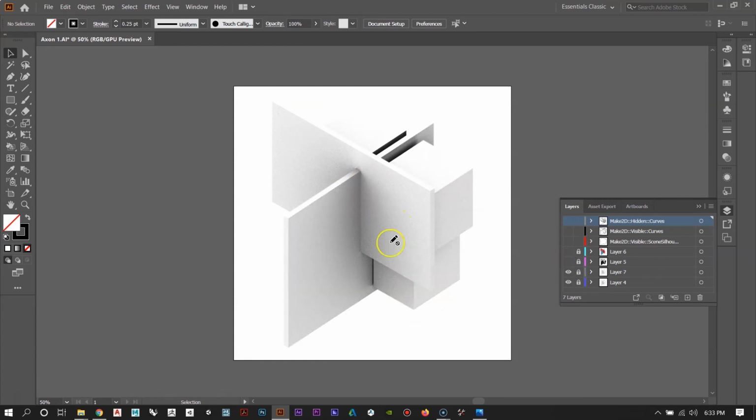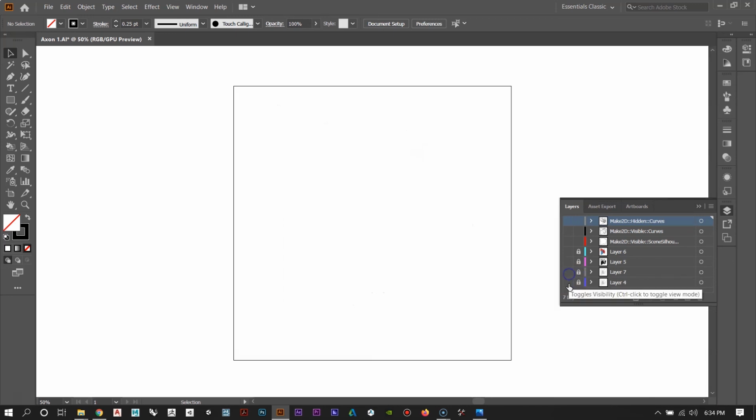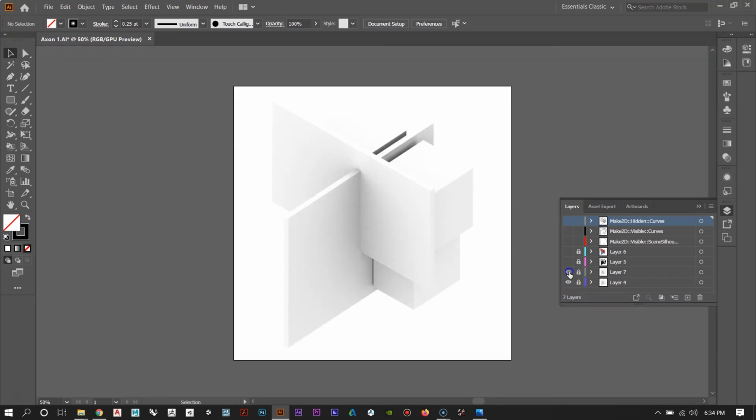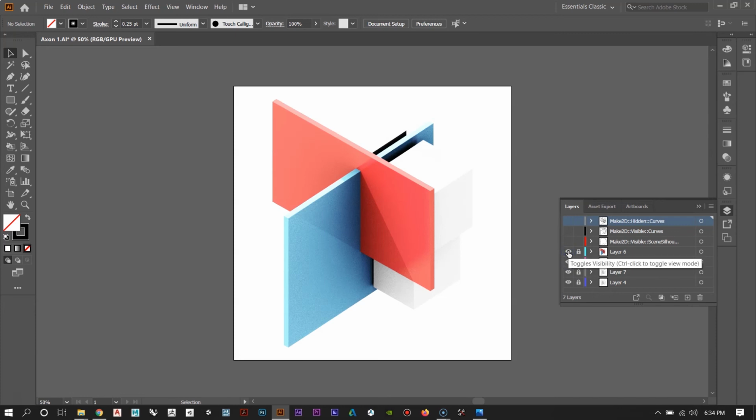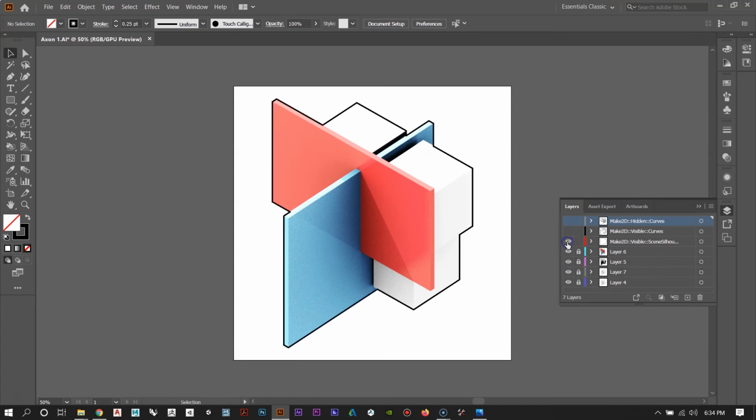And then we've got the occlusion layer, which I actually have 2 of them because I want them to be a little bit darker than just having the one. So I've got one occlusion, and then I copy and pasted the second occlusion on top just to make it a little darker, and then shadows, color, and then your 3 line types. Okay, and once you overlay all of those on top of each other, they produce sort of a nice quality diagrammatic image.